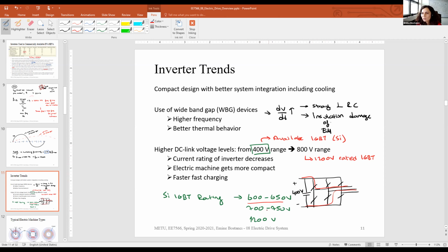Okay, and why do we have the IGBT, so common IGBTs have the 600 volt rating, not the 300 volt rating? Of the rectifiers this time. Exactly, because if you want to decide on the rating of an IGBT, it could be 500, it could be 300, it could be 800, but I feel like, I'm not an expert on this topic, but I feel like they have to decide on this value, the 600 volt or 650 volts, so that we can use it in line connected systems.